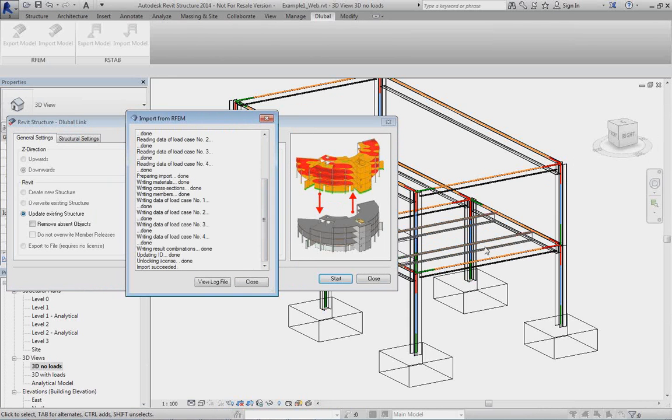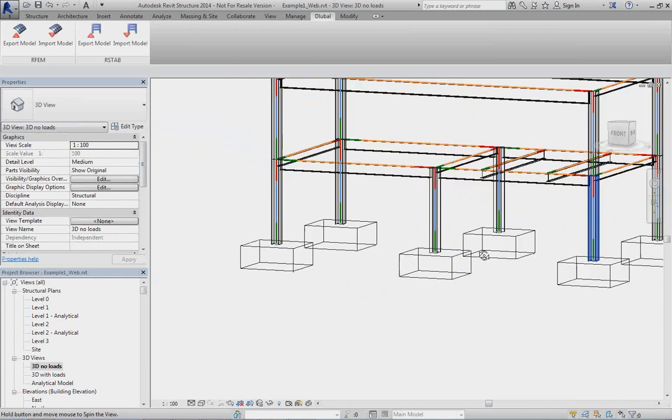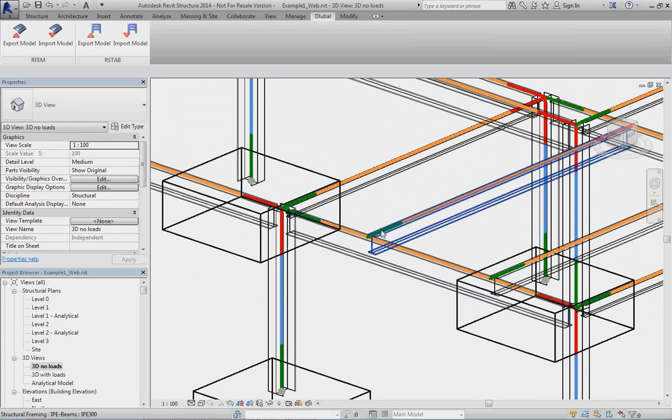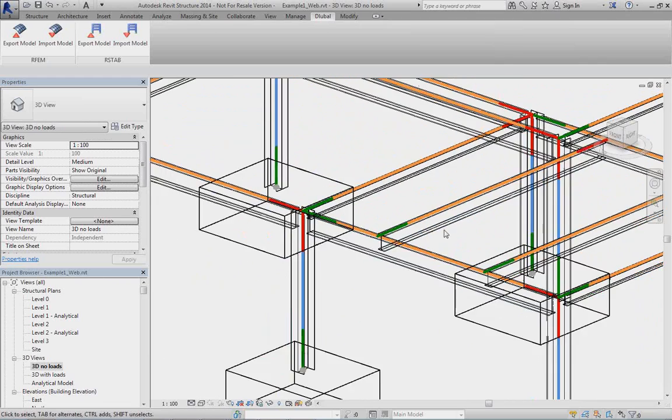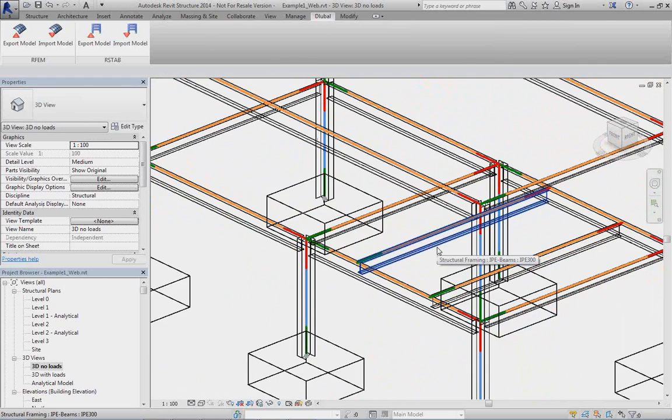my cross section. You've seen it has changed. It will update my cross section without touching the rest. And also please note the alignment of the structural model and the top alignment of the physical model have been unchanged. So those are important things, important concepts to understand.